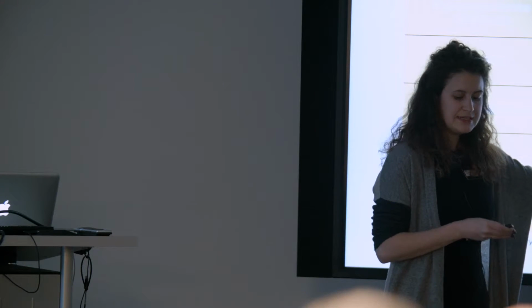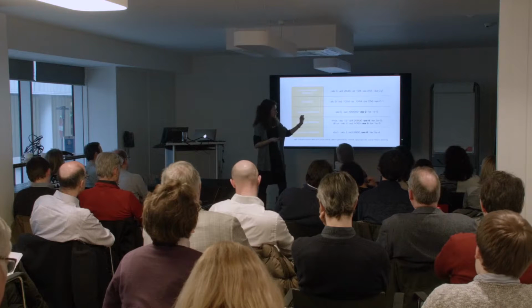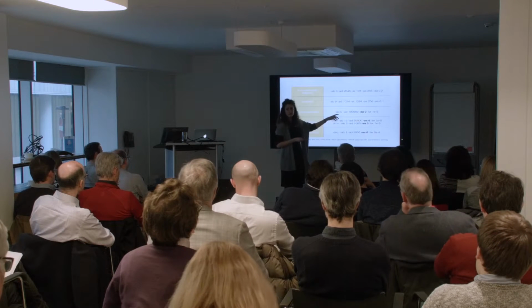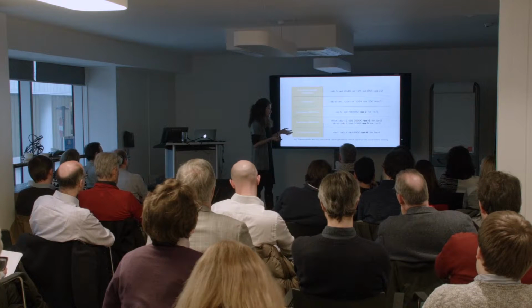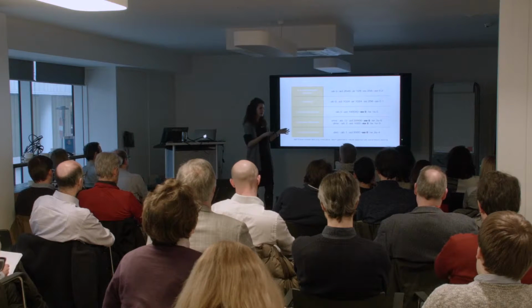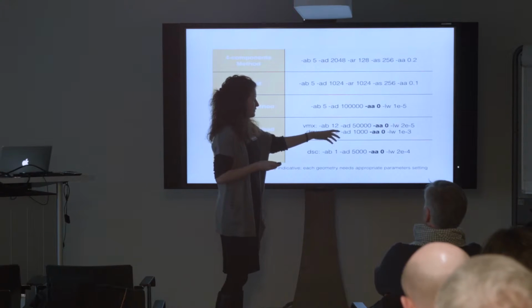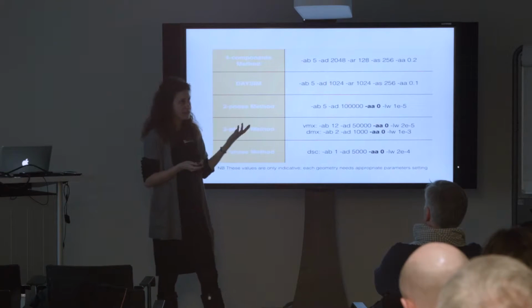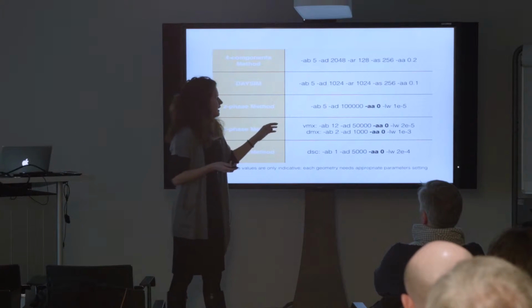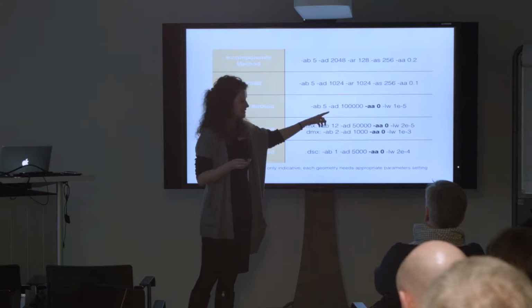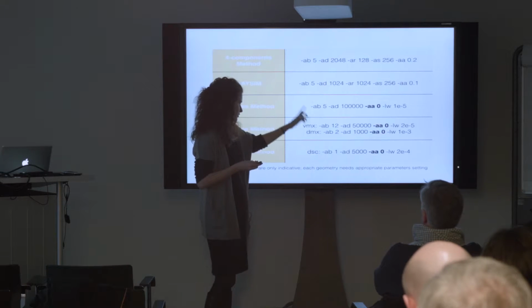First of all, in the Monte Carlo simulation, the interpolation part is switched off. So whatever value you give to the ambient accuracy and ambient resolution, it will be overwritten as 0, because it needs to have that switched off in order to keep track of the origin and destination of the rays. So AA will always be 0. And to make up for this decrease in accuracy in the results, we need many more rays sent around, so a much higher value for the ambient divisions. And that's true for all these methods.